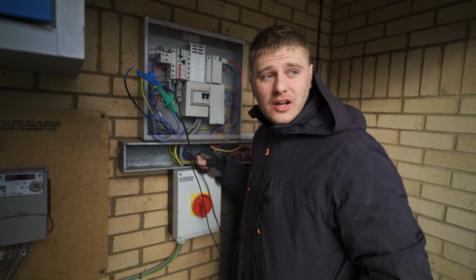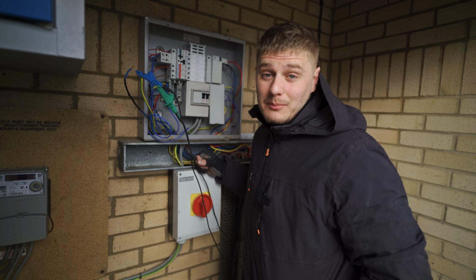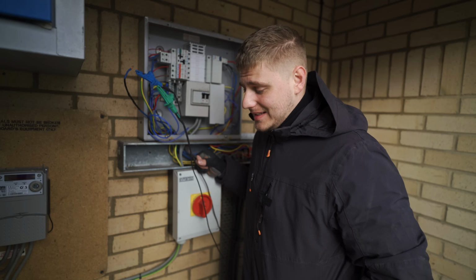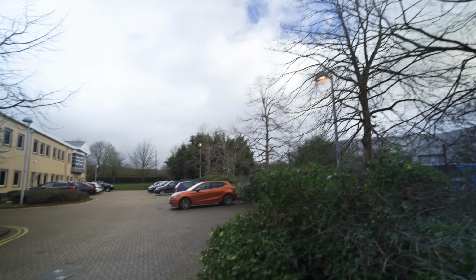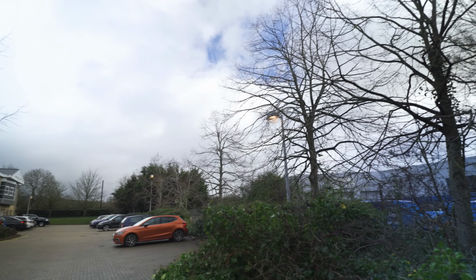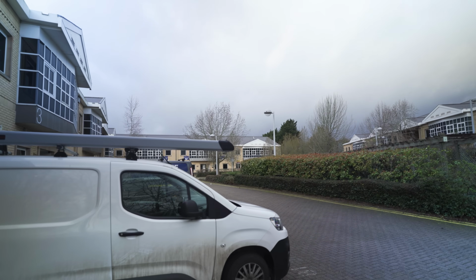I'm going to get this locked up and I'm going to run around the lampposts with you guys and see what we can find out. So these are the lampposts in question. As you can see, I've got the perimeter ones on. It's this middle row here, basically, all the ones that are off. So I'm just going to run round, pull all the fuses hopefully, and then that will allow me to work out whether it's a short circuit or an earth fault. Once I know that, I can then try and pinpoint exactly where it is.